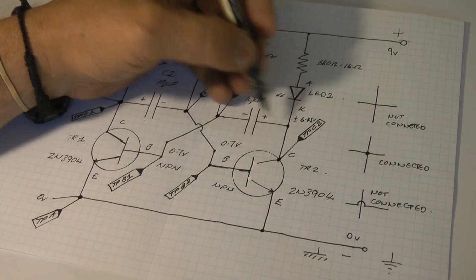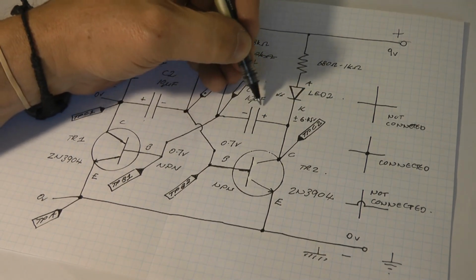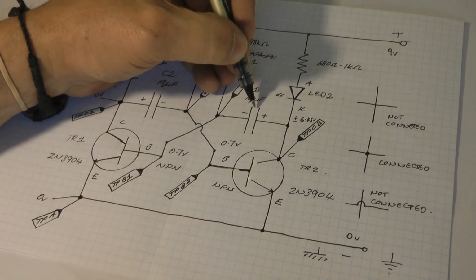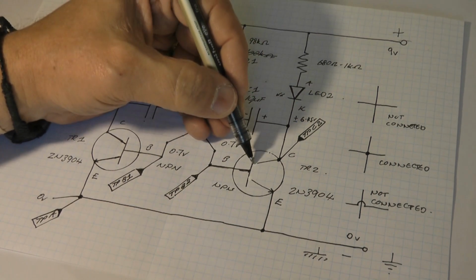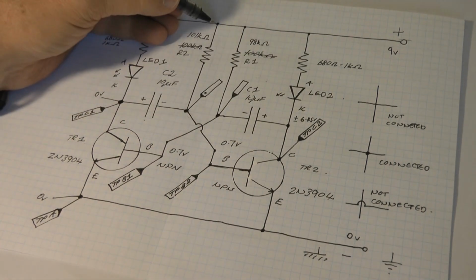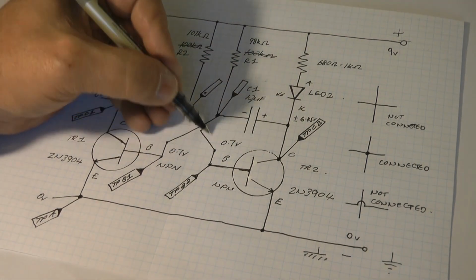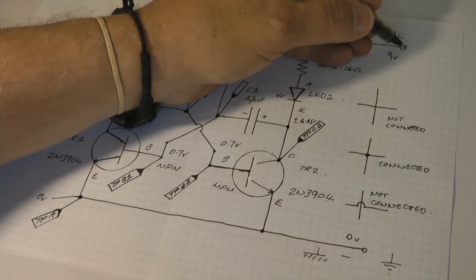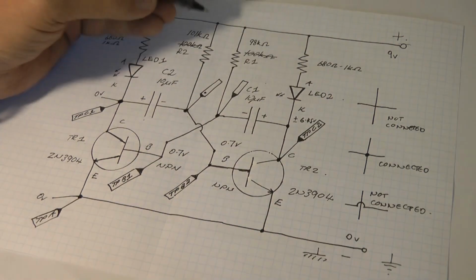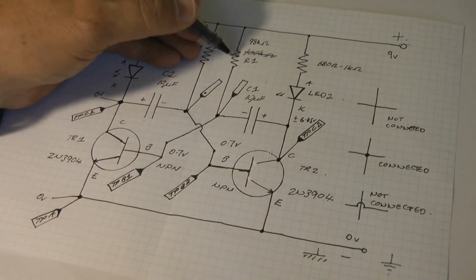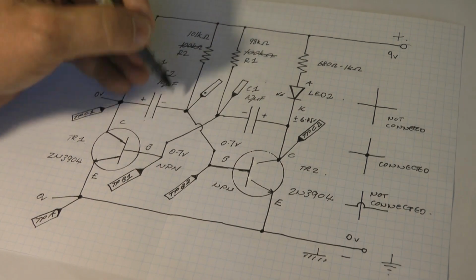So now this capacitor starts to charge up. At the same time that this capacitor starts to charge up and this transistor is acting like an open switch, the base point is again charging, because as long as power is connected here to there with our battery, these points are always going to be charging up until they're knocked down.